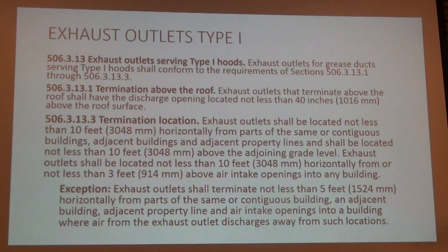Well, that's why they need to make sure that it's located 10 feet away or directed away from the property line. Have it directing back toward that way instead of directed onto the building. So if you've got an up-blast fan, how are you going to direct that away from the lot line? They do make an attachment that goes on the outlet of the fan.